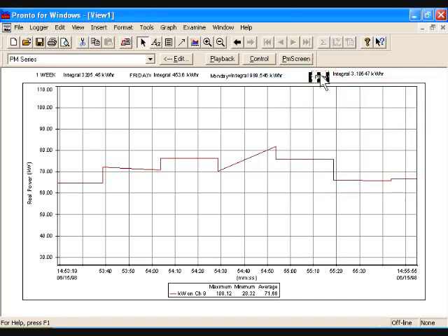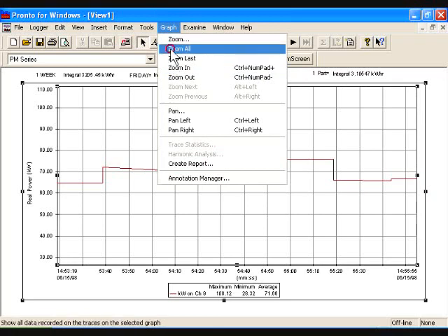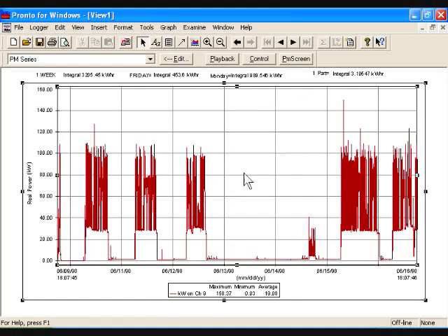Say okay, and so at the end of this session here, what we're looking at now, and we'll go back and get the original graph back on here. So here is the kilowatt demand during the 1 week of this assembly line. 1 week's kilowatt hour usage was 3,205. One day, Friday, a light day, was 453. A heavy day, Monday, was 989 kilowatt hours. And to make just one part was 3 kilowatt hours, basically 3.1 kilowatt hours. This is extremely powerful. Now, if you wanted to, you could just click over on your printer icon here and print this.